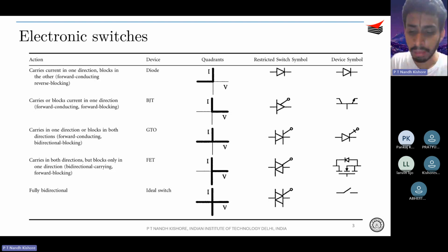So similarly, if you want to turn on the SCR, you need to supply a high value of a positive gate current signal to turn on the SCR. For turn off of the SCR, that is not sufficient. You need to apply a sufficient reverse bias voltage, right? Only then the SCR can turn off. So you have a number of circuits which you may be studying in later chapters as well, which are known as commutation circuits, wherein you will study how to turn off these SCRs.